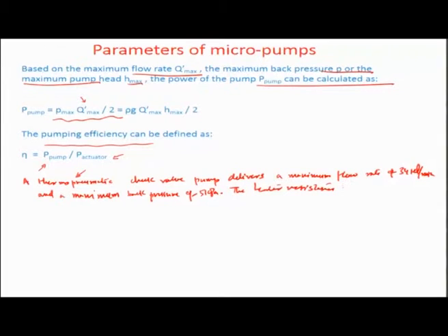In this particular case, the heater resistance for the particular design of this pump is around 15 ohms, and as a designer of these kind of small systems, when you are designing actuation at this particular scale, you must be very careful about the different parameters which are there to define the performance or operability of the architecture that you are designing for. So, the pump works with the symmetric square signal with the maximum voltage of 6 volts at 0.5 hertz frequency.